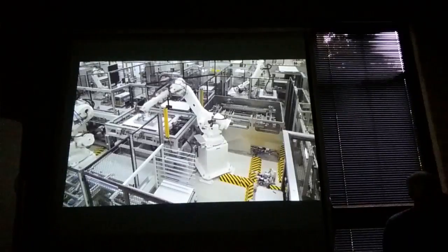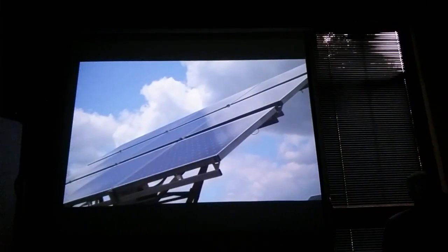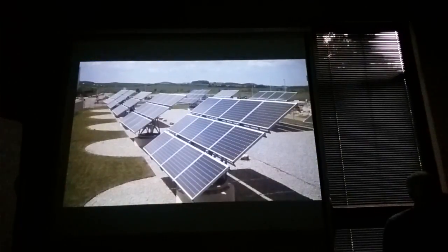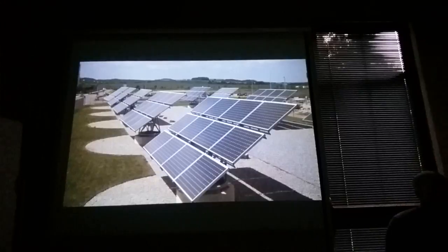Electrical conductivity. In a series of tests, the cell's conductivity is evaluated and sorted. Following the test phase, the solar cells are assembled. The cells are soldered together in such a way that the voltage accumulates. In a process referred to as lamination, the cells are assembled behind a pane of glass. As a result, they are protected from the elements for more than 25 years.